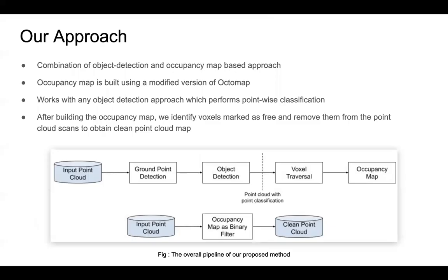We now present our algorithm in detail. We use Octomap for building occupancy maps, but we have modified it to favor representation of long-term occupancy states or quick updatability of voxels. Our algorithm pipeline looks as follows. It starts with a registered set of input point clouds from a LiDAR. We remove the points which are beyond distance r from the sensor origin to remove noisy data.